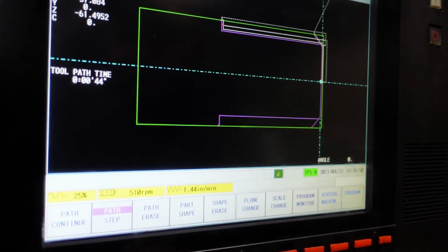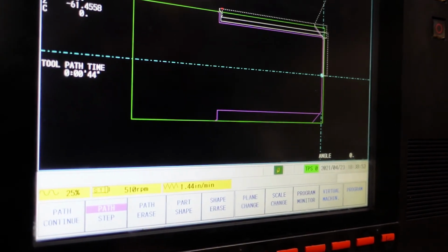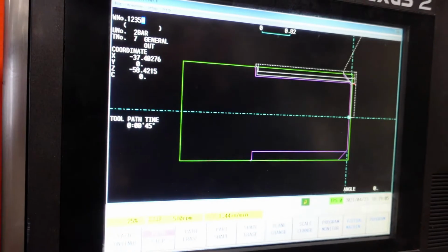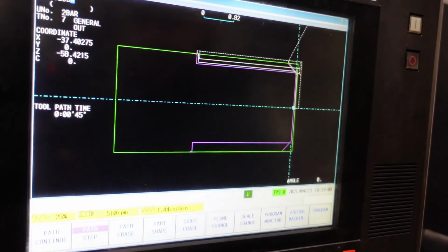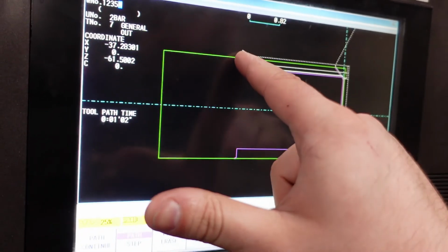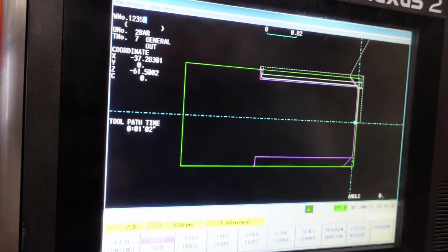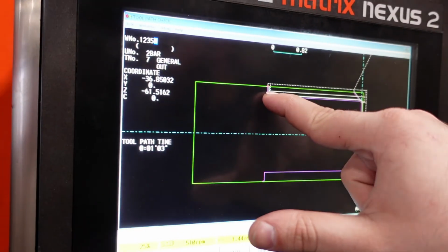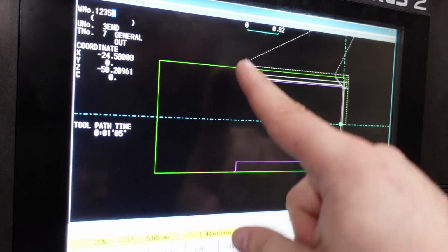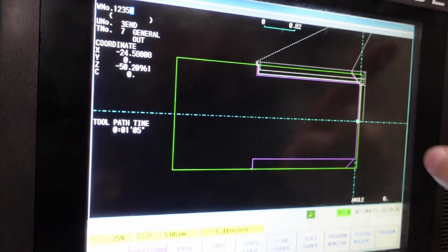It'll go up and X. It'll then miss everything. It'll actually interpolate its first rough pass to its second rough pass. That way there's a nice straight line. Then it will wrap it back down. It'll wrap it down to its start X position, which is what we were looking at earlier for our chamfer. It'll cut that chamfer, wrap it up, or it'll turn all the way back at its speed rate, turn up the rest of that Z tolerance that we had there, and then it will finish our chamfer. And it will wrap it home. And that will be the end of our program.